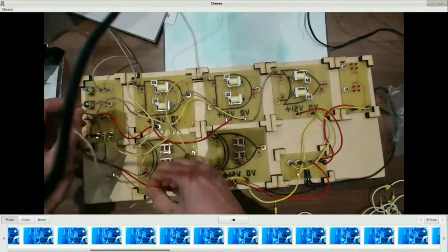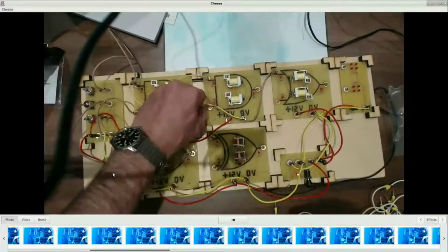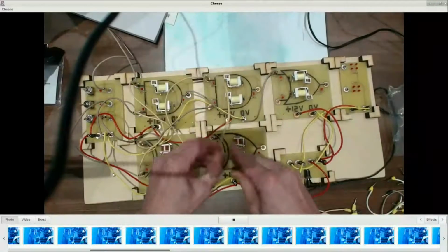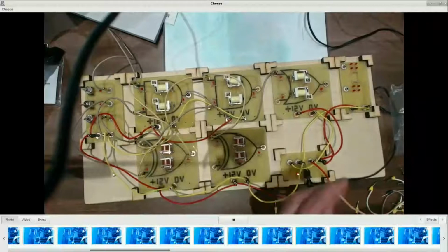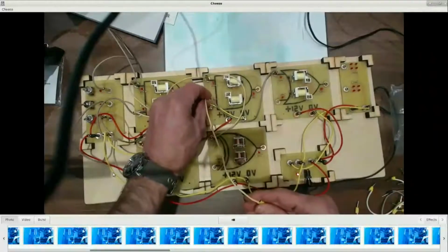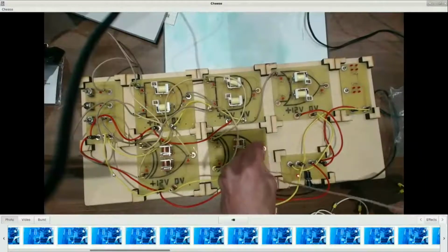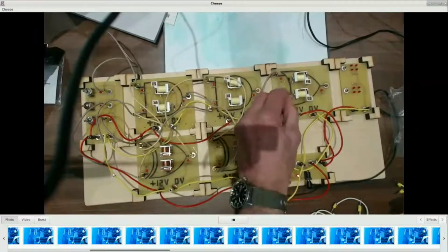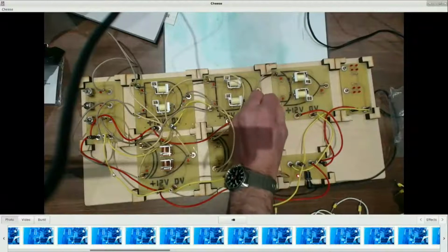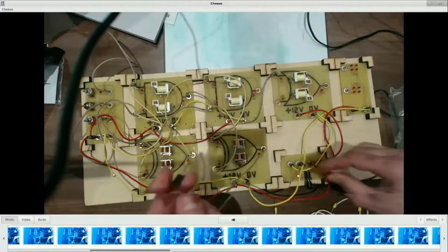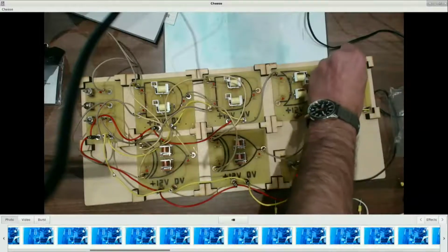So I'm taking this one here as my carry in. It goes to the inputs, same as the other one. So I'm replicating. That signal goes to the exclusive OR to make my other half adder. And finally, the output of my exclusive OR gate goes to the sum. We're building a circuit here. It's not going to work. So it goes to the sum gate there.